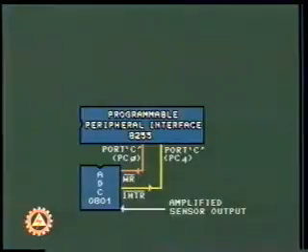Port A of the 8255 is used in input mode, and we connect it with the data lines of the ADC 0801. The processor reads port A to acquire the digital data generated by the ADC 0801 corresponding to the amplified sensor output.